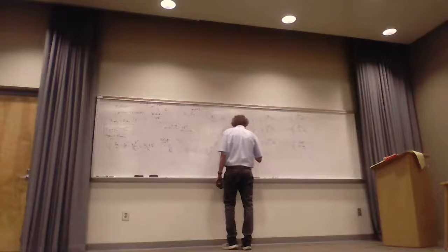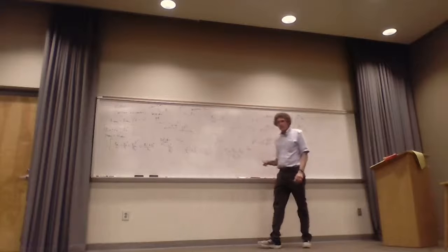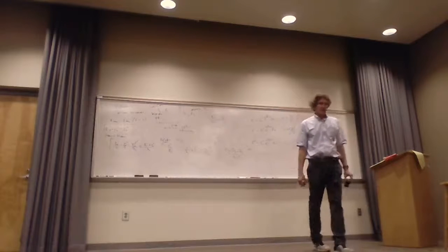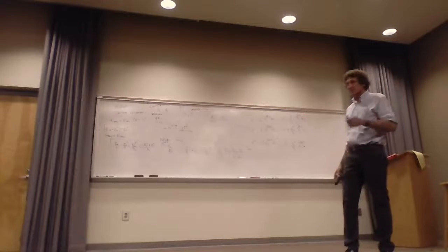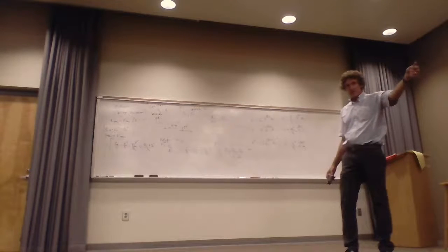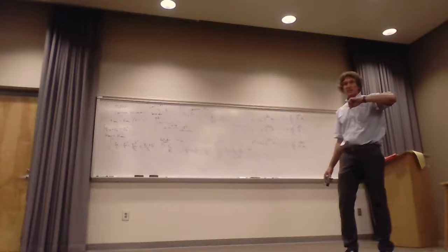And that is something very important. That's the reflection coefficient. Doesn't that remind you of transmission lines, where if you wanted the reflection coefficient, you took Z load, the impedance you went into, minus Z naught, over Z load plus Z naught? Go with me?